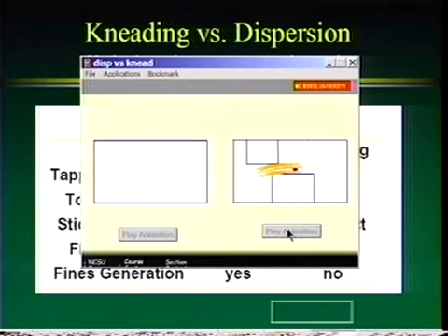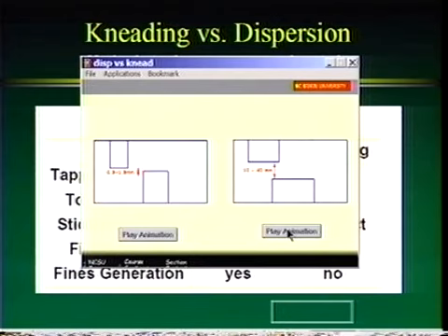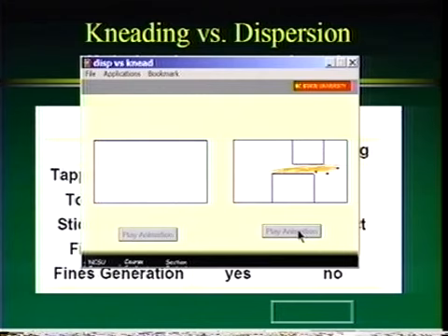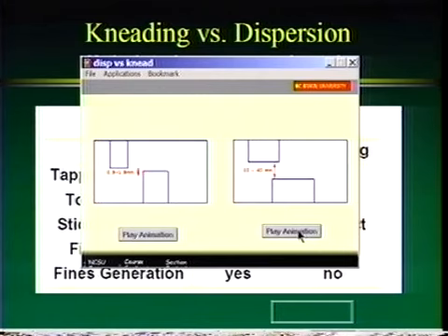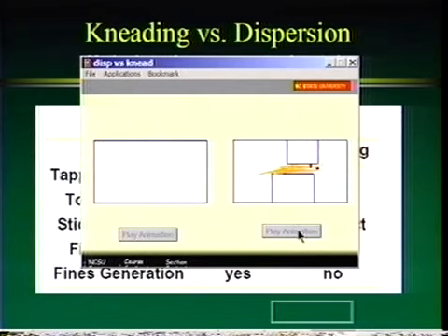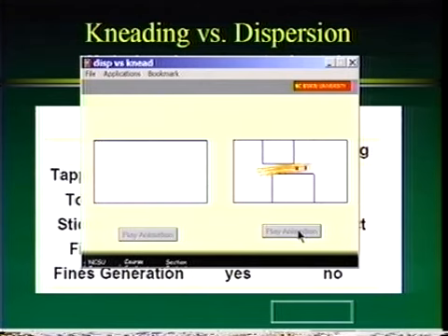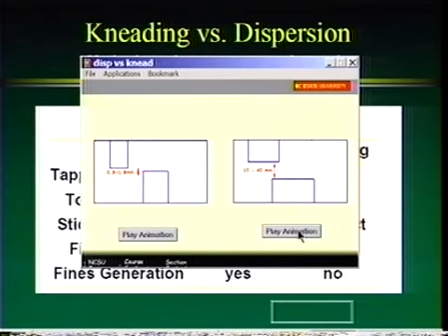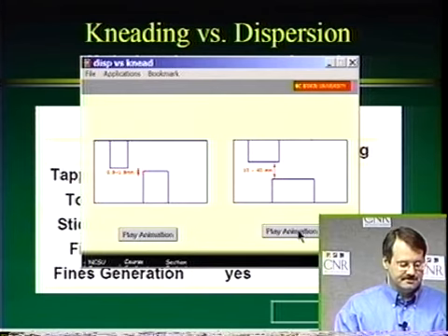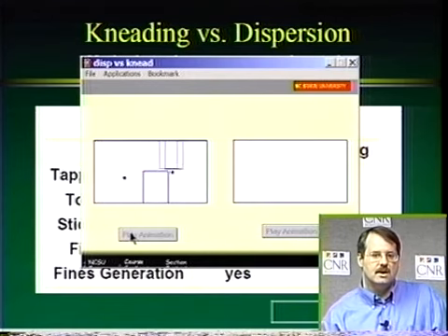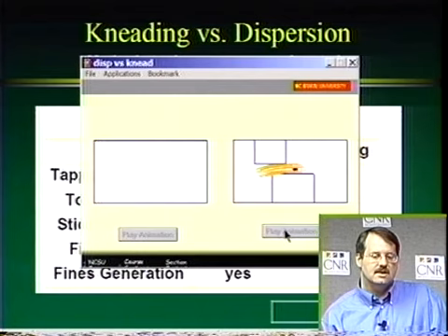So we see here that kneading is a much slower, gentler, fiber-to-fiber rubbing. I might not have the size scale perfect, but there are going to be very few fibers that are cut or pinched between the bars. There's usually going to be several layers of fibers, and each layer will rub against the next layer, with several layers between the two bars. So again, one last time: disc dispersion is pretty quick, kneading is pretty slow, and uses the fiber to impart the mechanical action.